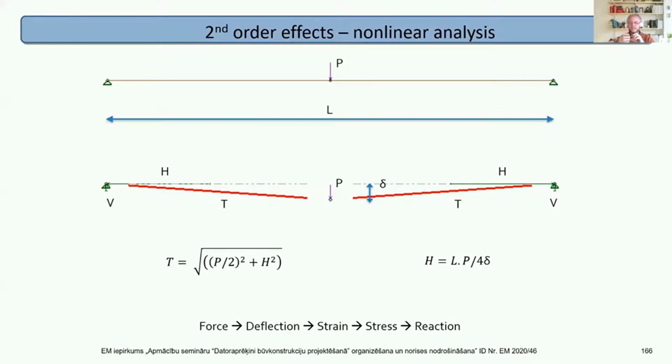That deflection creates a strain. That strain induces the stress, and the stress induces the reaction, and the structure will deflect until the reaction to the applied load is equal and opposite to the applied load. Linear analysis, we can usually just go, it's all there. Non-linear, we've got to search and iterate through until we get to that point.